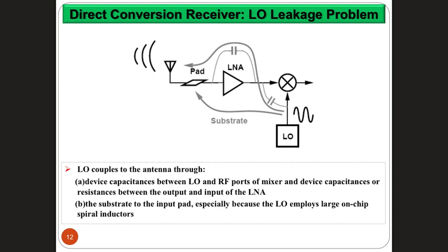I have a question. Does this relate to the DC offset? I was working with the HackRF, and when I was looking at higher frequencies, like the demodulated frequency domain of, for example, the FM modulated signals, so I'm looking at the FM band, I was always noticing that there was in the middle, at zero hertz, always a DC offset. Was this related to the local frequency running at higher frequency? I have no idea. It might be your signal itself has a DC. I tried shifting it, but the DC offset always was there.